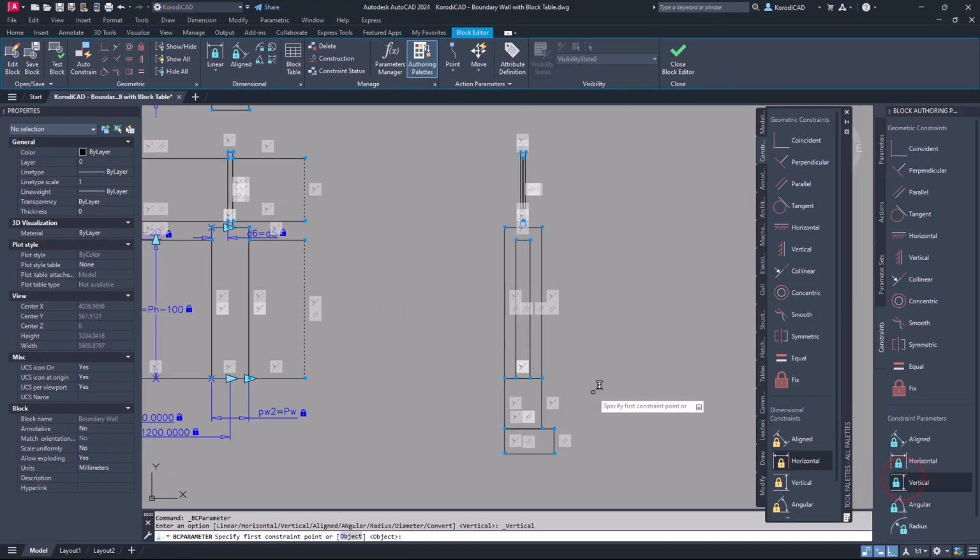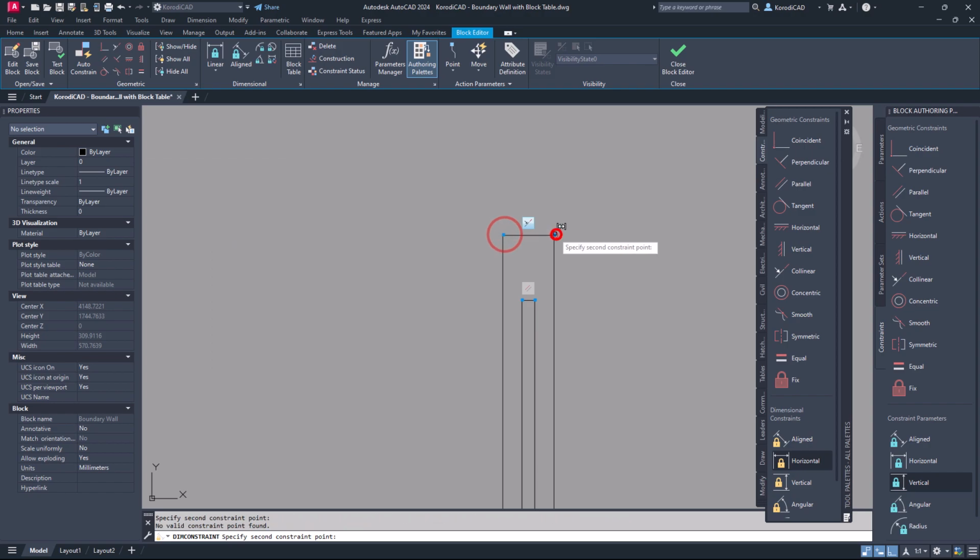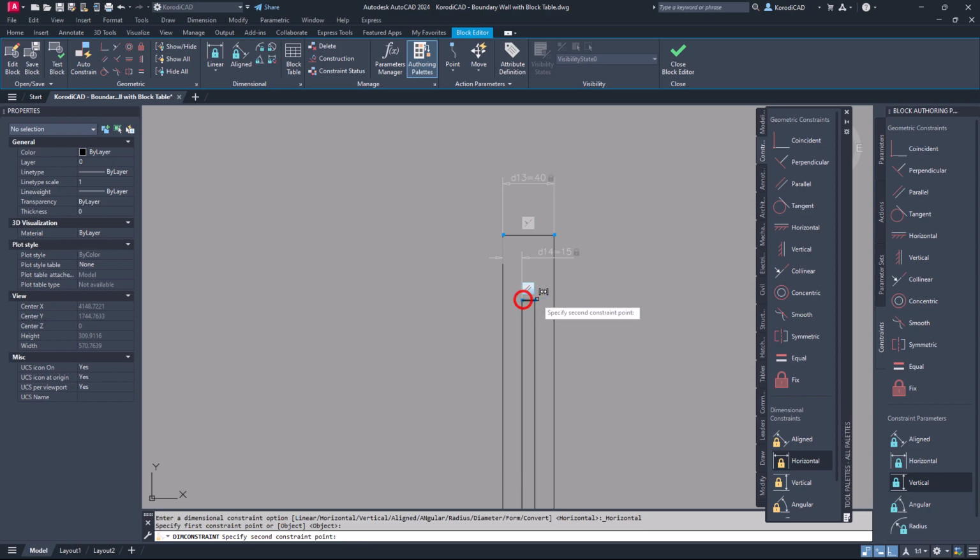In the cut view, I will place only one parameter, the height of the foundation. All other dimensions will be solved by dimensional constraints. Fix the fence post width here too. Then do this with the distance of the fence and the fence itself. Also fix the vertical distance.